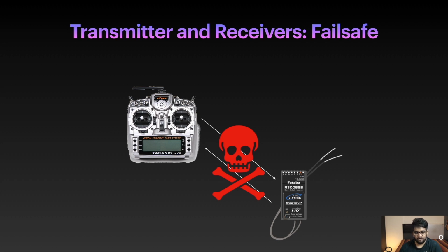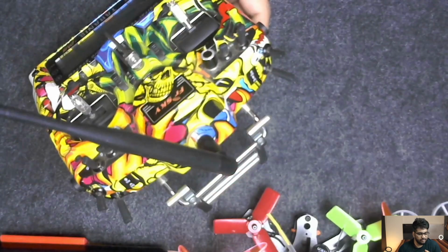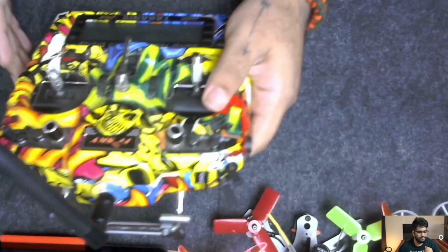One thing you can do is cut off the motor and let the drone fall like a rock. One thing you can do is let the drone fly at the same altitude it's flying. One thing you can do is let the drone ascend very slowly. Depending on that, you can program in your flight controller what you want to do when the situation of failsafe happens. The last thing I want to show, we need to go to the overhead camera.